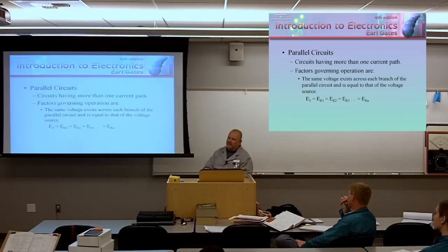Voltage is constant across a parallel network. Most important thing you need to remember. So when I say that, what's the most important thing about a parallel circuit? Like church, you all repeat after me. Voltage is constant across a parallel network. Okay? The second most important thing about a parallel circuit is that it is also known as, police lingo, AKA, also known as what? If a series circuit's a voltage divider, what's a parallel circuit? It's a current divider.